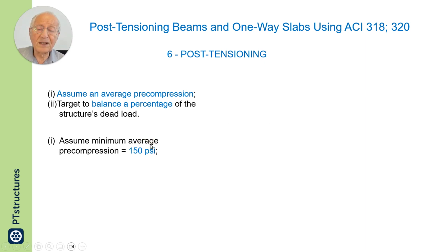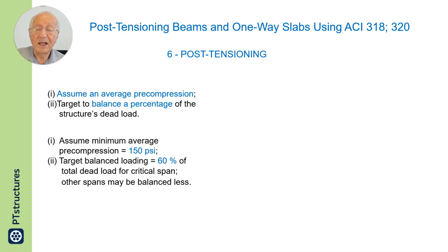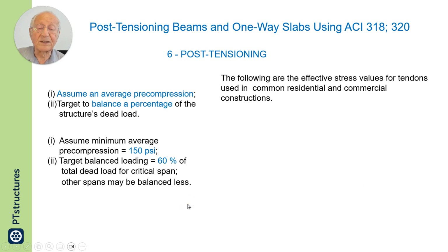In this case, I have made an assumption of 150 psi. This is not by calculation, this is by assumption. And I make an assumption to target balancing 60% of the dead load. These are my inputs as design engineer, not obtained from calculation. These are inputs.